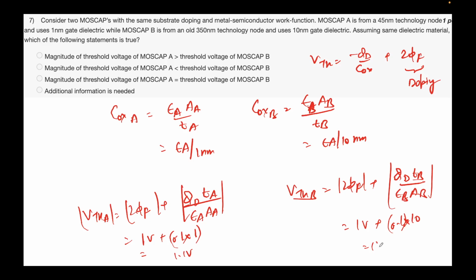Threshold voltage decrease actually creates problems, because these capacitors, and in fact the MOSFETs which are made on them, are used in switching circuits. If the VTH is very low, a MOSFET can be turned on and off just by some random noise. So these are some peculiar things that engineers have to take care of. Also, when you are operating with 1 nanometer thick oxide, we have already talked about tunneling. The electrons can simply tunnel through, because 1 nanometer is very thin, only a handful of layers of silicon dioxide. There are ways to fix that by using high-K dielectric and whatnot.